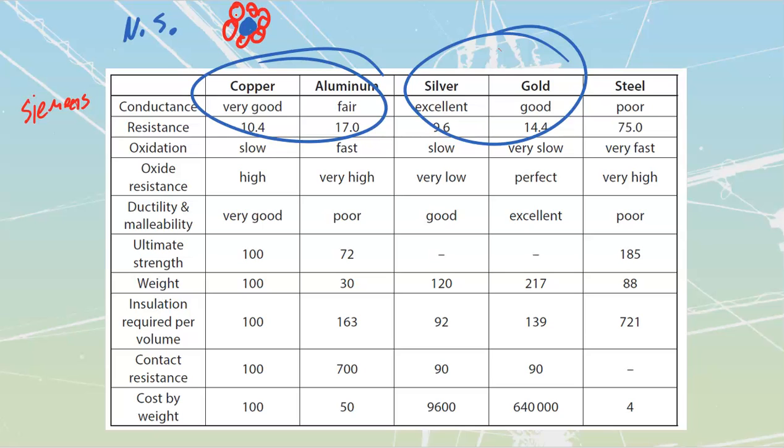The other place we see steel used is in the actual grounding electrodes themselves. Grounding rods and grounding plates are going to be heavily zinc coated so that they resist corrosion, which is what we call galvanization, the zinc coating. They're going to be heavily coated so that they do not rust out, but they're still going to be made out of steel.